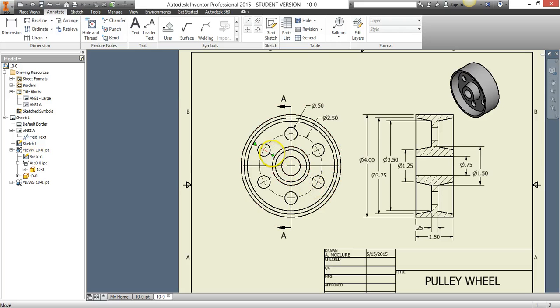Now what we can do is go ahead and drag these so that they meet in the middle. You can do this for all of these, so it actually is more of a realistic center line, and these should be fine right here because we have the section line going through it right now. So we can go ahead and pull these center lines out as well, since these center lines do belong to this circle, and the center lines right here, the vertical ones, we won't be able to see those because of the section line anyway.